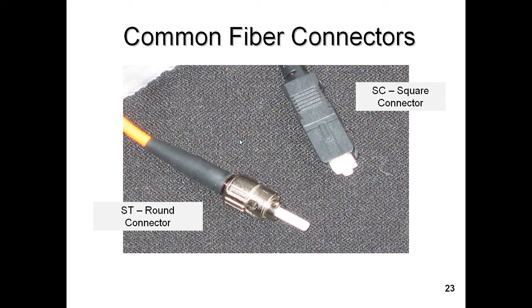And if you're looking at fiber optics, you need to look at A, what kind of connectors do they have, and B, when you're looking at the optoelectronics, which are the boxes that are going to do the signal transmission and receiving, you need to look at what kind of connectors they come with. And be aware of whatever changes you may need to make: if you've got a device that's an SC device and you need to terminate to an ST device, that's not a problem at all.